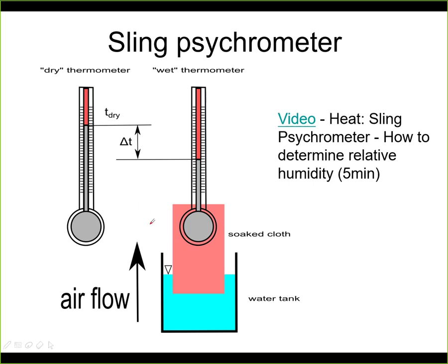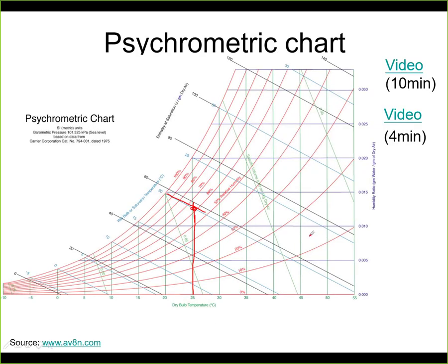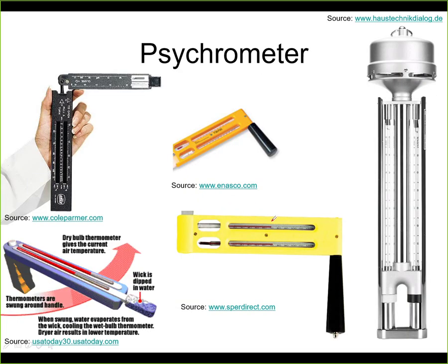It is not very suitable for small enclosed spaces, because very soon this would change the relative humidity of your device. So for example, if you have a small box, small room, then soon it will increase the humidity above what you actually measure. Okay, so that's the second hygrometer. Again, we'll see it in the comparison at the very end.